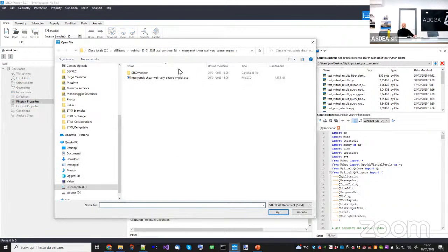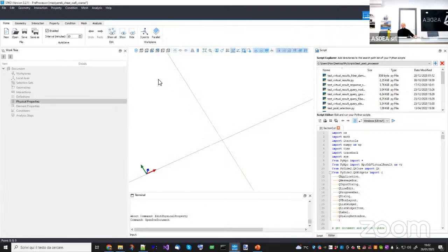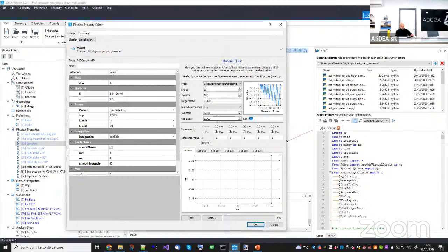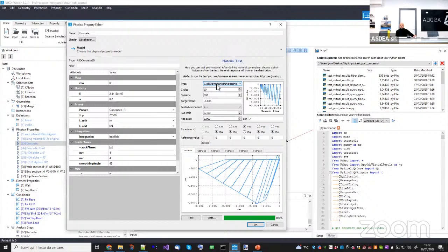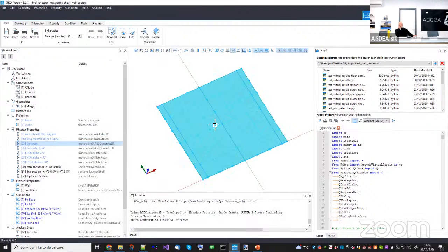Now, if we move to the shear wall with the implicit scheme, which is this one, the mesh size was 0.4. As you can see, if I use 0.4 here as a test, let me do it monotonic, 0.001, you will see that the behavior now is not so brittle. So I think that I will reduce these instabilities. Everything else is the same. Here, I just changed the mesh size to 0.4.